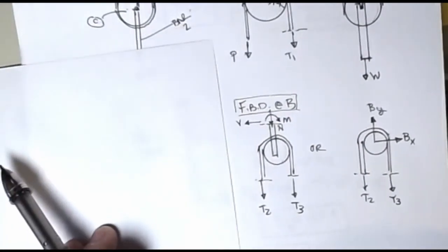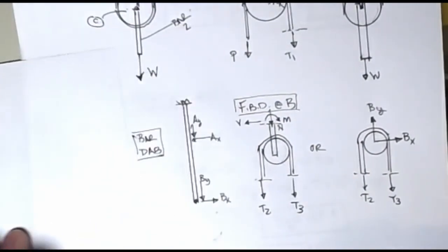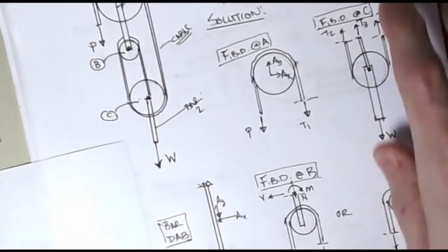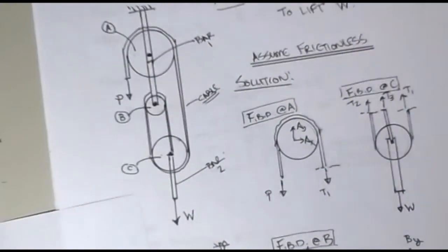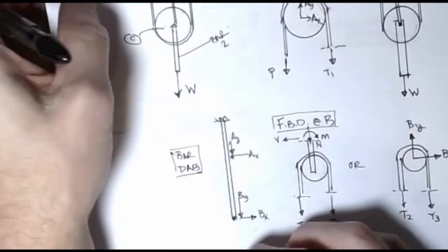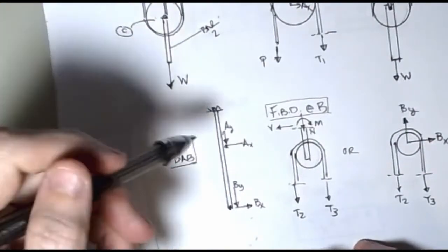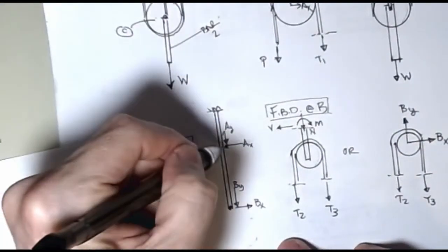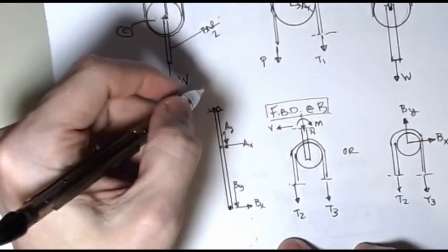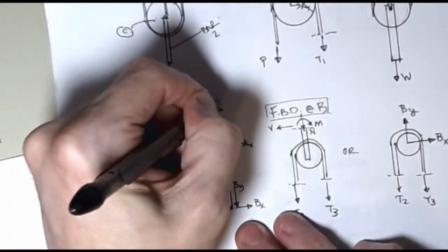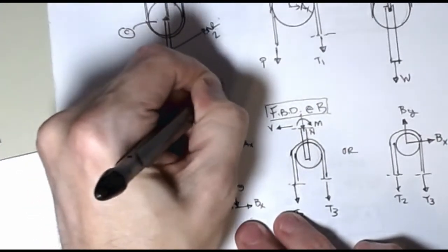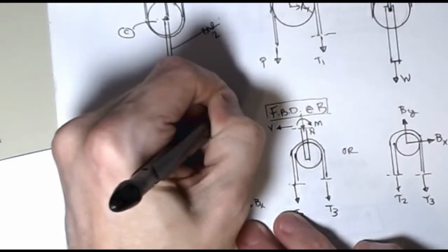Now, I can also draw a free body diagram of that main bar that we had happening up at the top, the bar that contains B and D. So if I looked at this bar here, the free body diagram of this bar, you'll notice we had where the pin was connecting at A, and where the pin is connecting at B, and then I get my moment at D, I get my Dy, and I get my Dx on that guy.